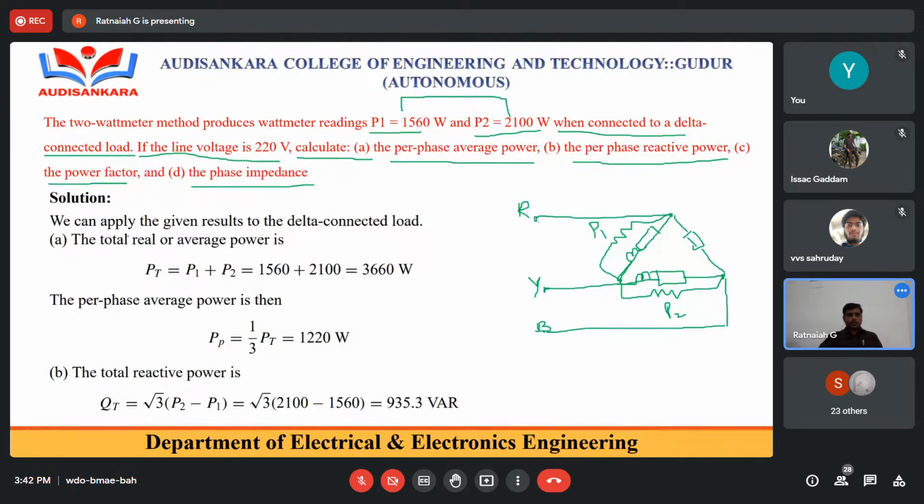Now the line voltage is 220 volts. Obviously the line voltages are displaced by 120 degrees, but here the phase shift is not required, so you can take 220 volts directly. But we don't know the value of Z. This is what we are going to find. What is the impedance per phase? I think this is a balanced load. So he is asking about the per phase impedance, and we don't know the value of Z.